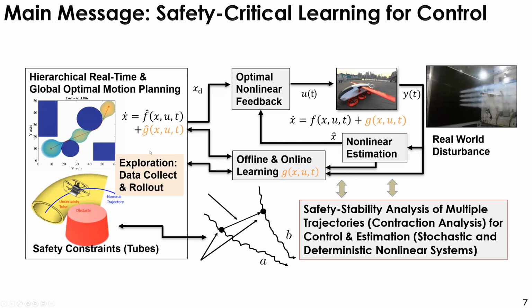And let's talk about the planning. Yes, this is only the feedback control and estimation part. But if you look at this box here, we also have multiple methods that can be used to do motion planning. Obviously, if you have to fly fast in a very obstacle-rich forest, then you have to have a very good perception method, but at the same time the vehicle moves fast, so you also have to do very fast computation to avoid obstacles.